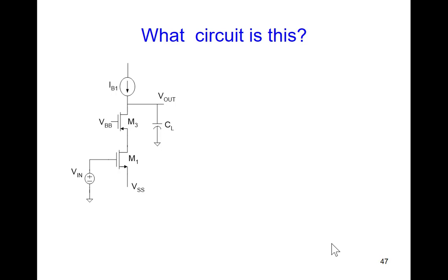We have the M3 will also behave as an amplifier versus just a common base. So the drain of M3 goes into the drain of M1 goes into the source of M3 here, right? Yes. But since we have a current source biasing, M3 stays a 2-port in the small signal. It won't become a 1-port model.